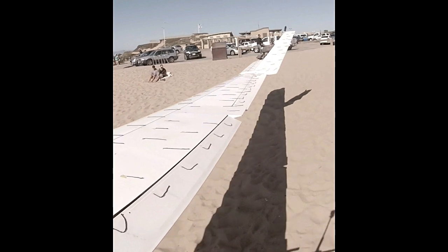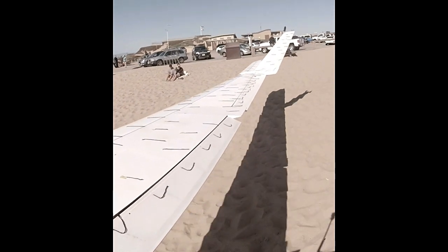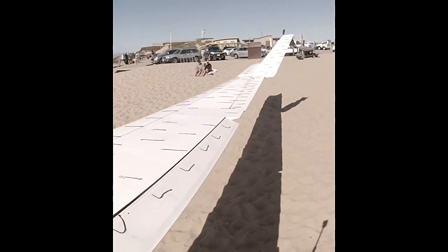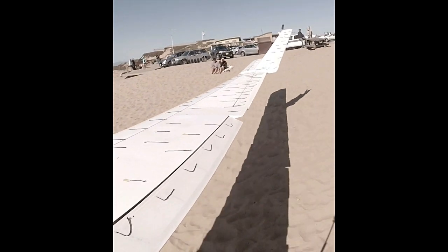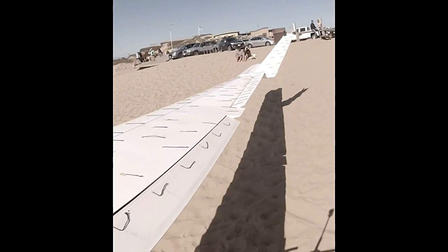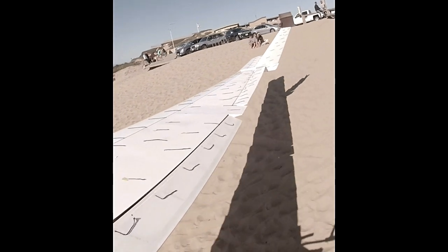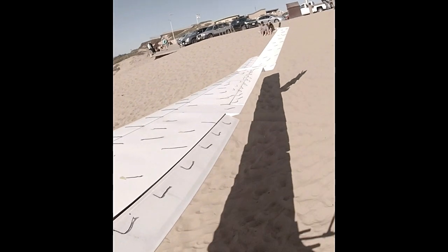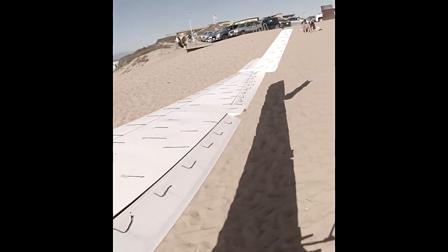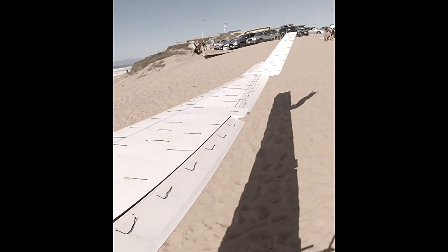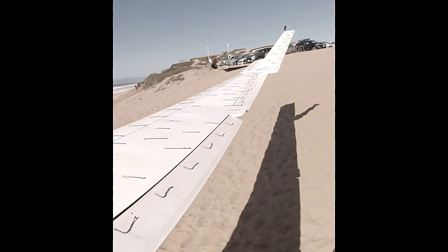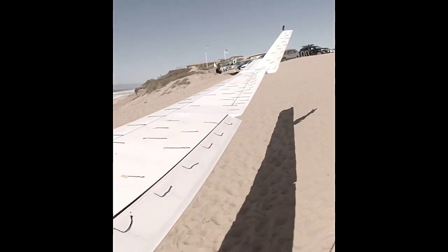However, that down elevon, separated flow on half of it or more, and it's creating a lot of extra drag. And then as I pull in up elevator to take off, we'll see the flow reattach. Everything's fine. There's the rotation, and there's the start of a stall there. That might be a laminar separation bubble. I don't know. The elevon's back down. Now we have a bunch of spanwise flow. Not good. Not helping the situation any.